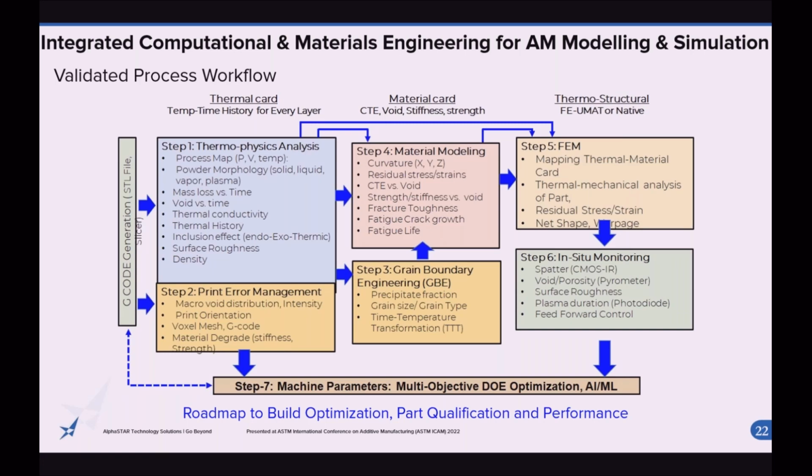And so once we have full thermal distribution versus time and our assessment of material mechanical properties, we can then, at its location over the overall build plan, over the G code, bundle or map all that information into a structural model for thermal structural analysis.